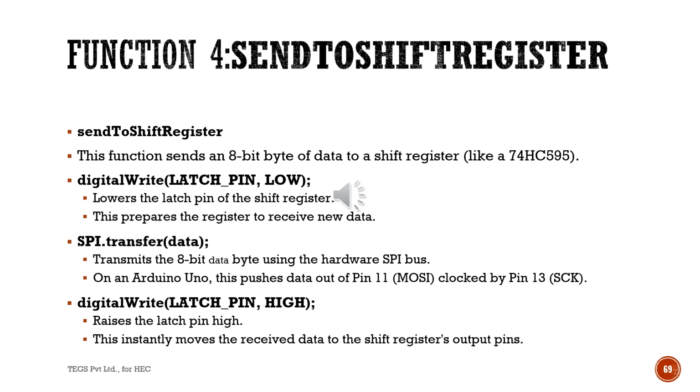SPI.transfer transmits the 8-bit data byte using the hardware SPI bus. On an Uno, this pushes the data out on pin 11 MOSI, clocked by pin 13 SCLK. The digitalWrite latch pin high raises the latch pin high. This instantly moves the received data to the shift register output pins.